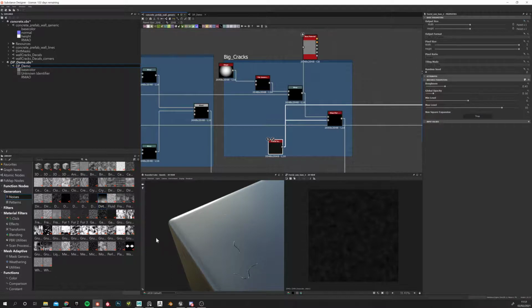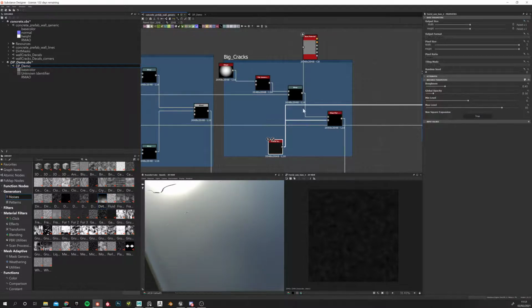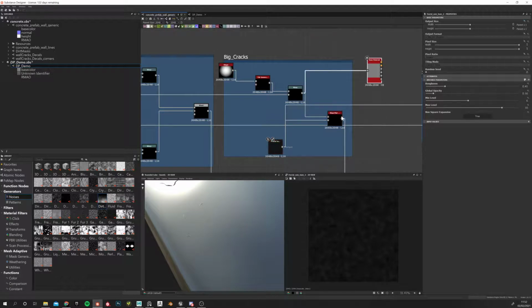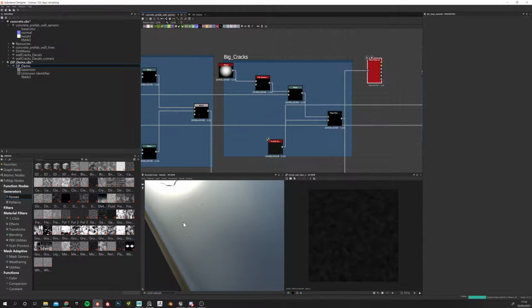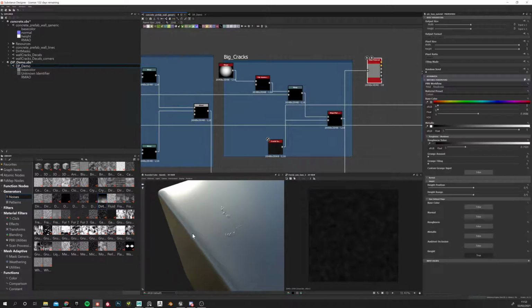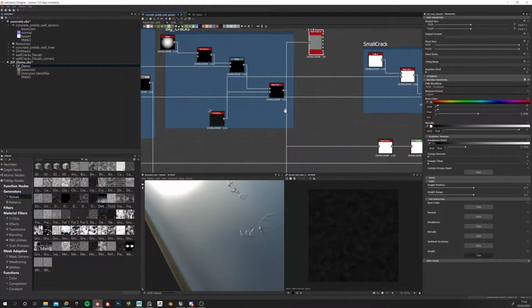You can see these lines, you see, I warped them. That with a higher intensity, obviously, and then I did the same fractal nodes, and then I did the slope warp, and it gave me this. You can see, look, something that is similar to the cracks.